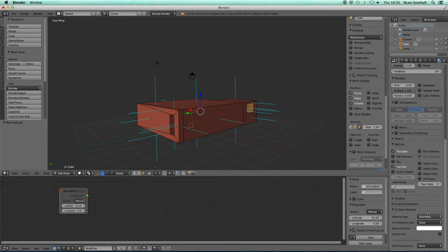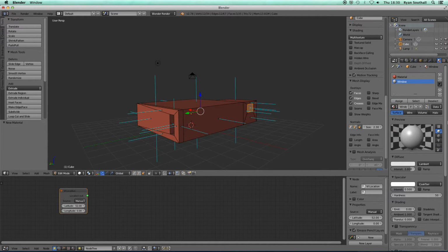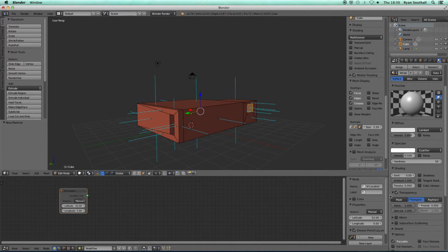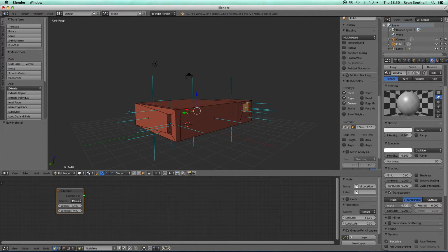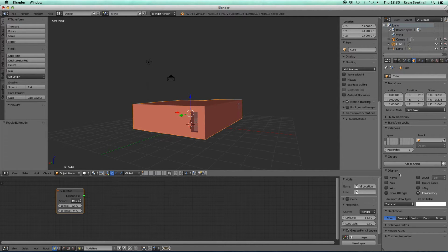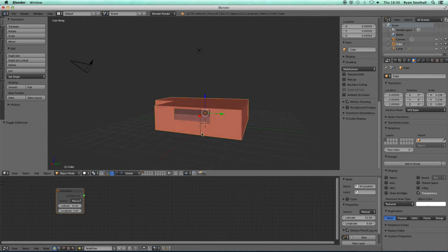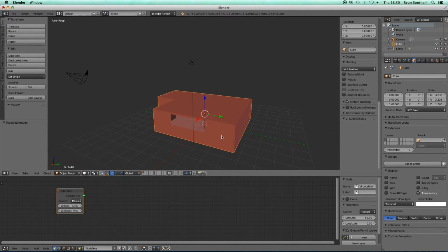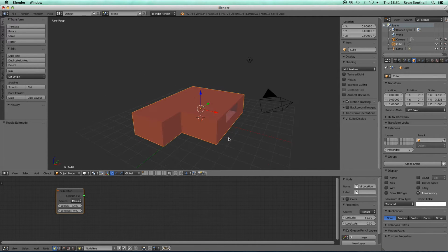And these settings are in the v0.4 material tab, which generally sits at the bottom of Blender's material tab. So that is more or less the absolute minimum setup for a lighting analysis. I can also just make Blender appreciate that those window faces are transparent faces. So that's the general shell setup for the model.